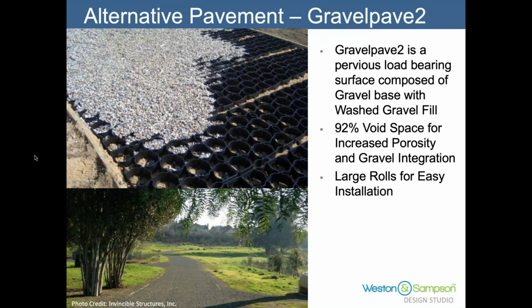So the voids are filled in, and what it does is allow water to infiltrate through this surface and into the ground, minimizing potential impacts to roots or the forest understory. These are pretty easy to install, lightweight materials, and they also have the advantage of significant available loadings. So up to even fire trucks or buses could pass over some of these systems if designed appropriately. There's another way that trails can be extended through resource areas without having to completely hollow out any of the existing trees or roots and resource areas within a corridor.